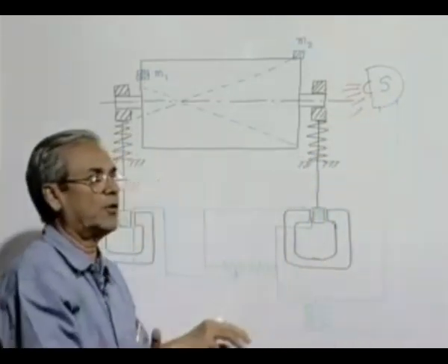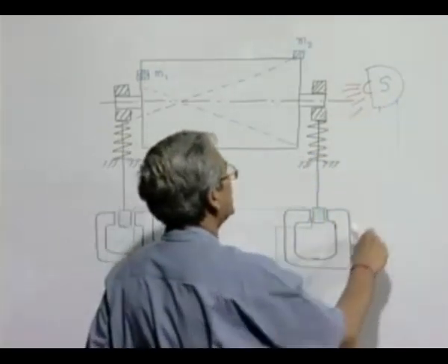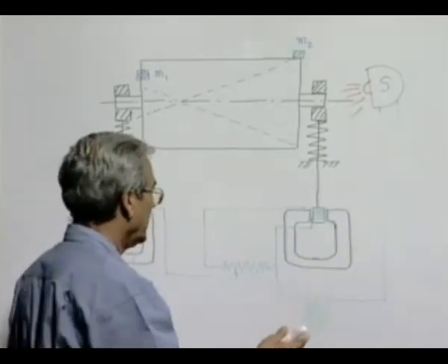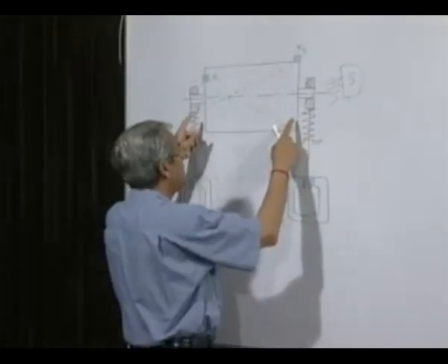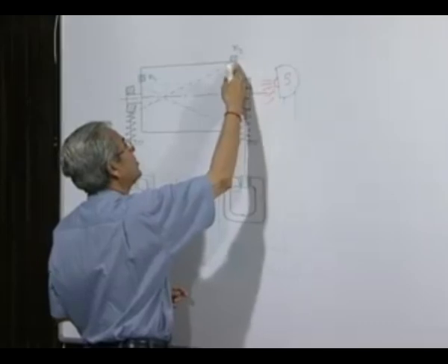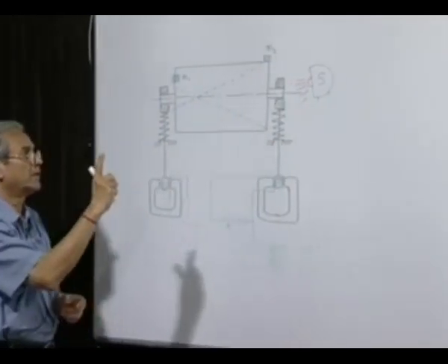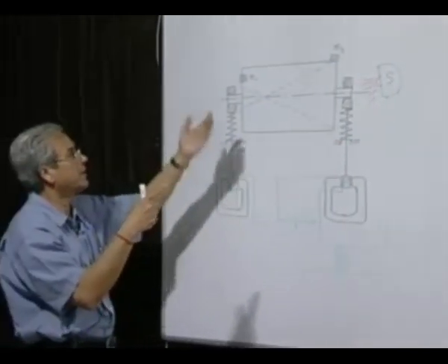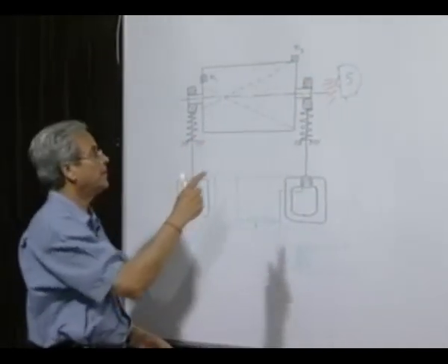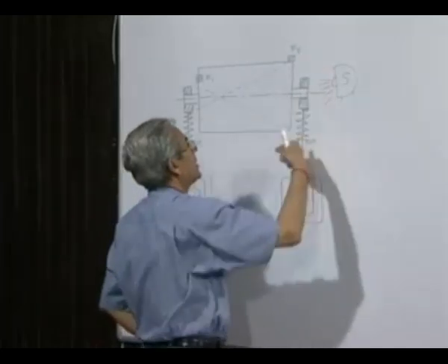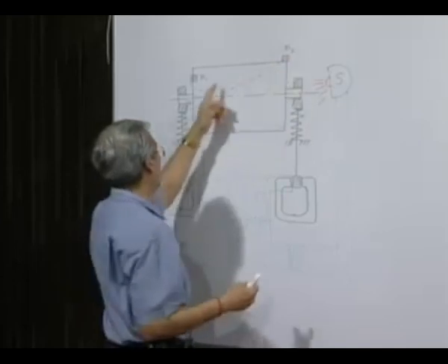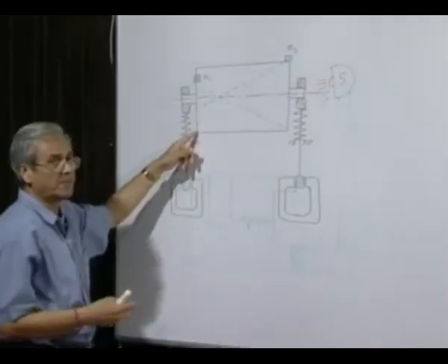So, now whenever this moves up and down and this voltage changes its direction, this stroboscope will flash for 1 microsecond as soon as the direction or the sign of the voltage changes. It is arranged in such a way that when this is at the top position in its vibration, it flashes. If it rotates at reasonably high speed, the flashing will also be at reasonably high speed, and you can see the marking. There will generally be a protractor kind of arrangement which will show you the angular position when this is at the highest, or where M1 is the lowest.